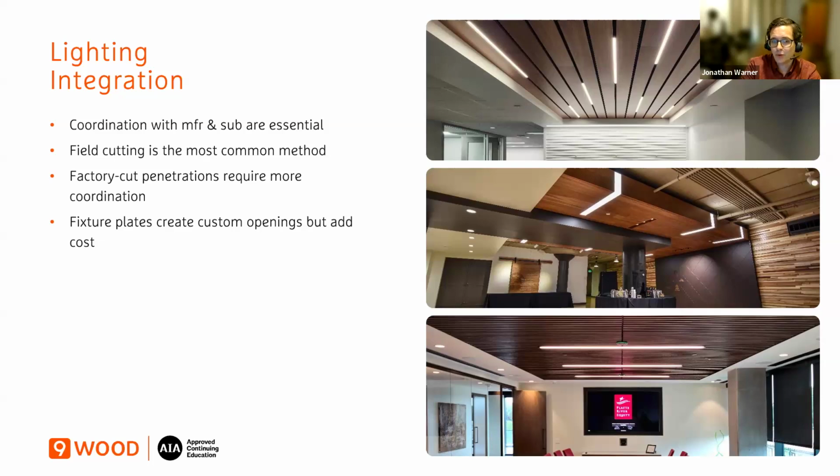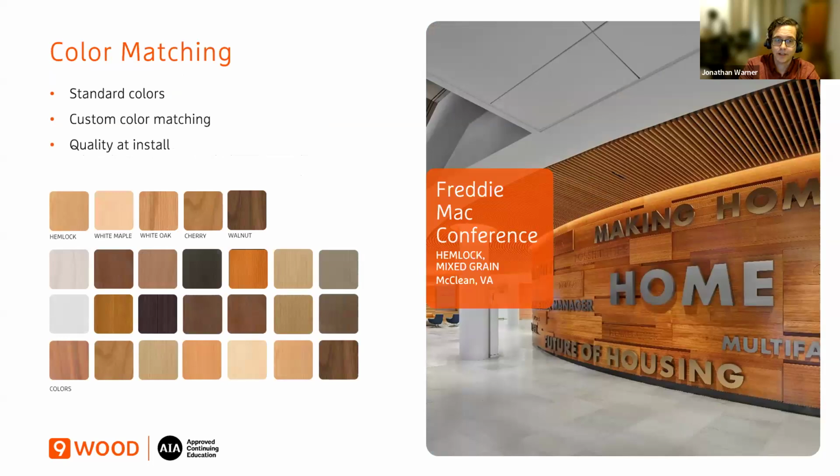It can potentially be more precise if necessary, but it will require more coordination and can have an additional cost, either on the labor side. Fixture plates can create custom openings and they're available, but they add cost. So the big idea here is there are lots of options available, but make sure you get the proper details from the manufacturer, and they have a plan to coordinate that all the way through installation, so you don't run into any headaches or issues coordinating all the fixtures with accessibility and other things going on.